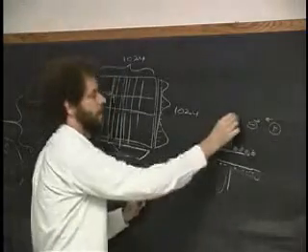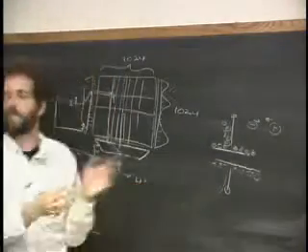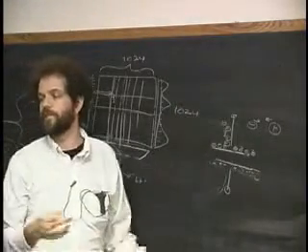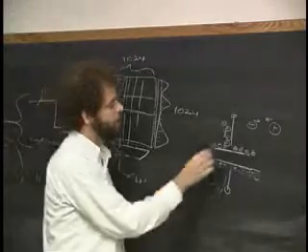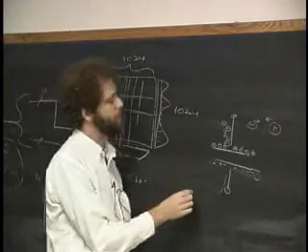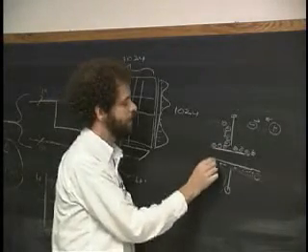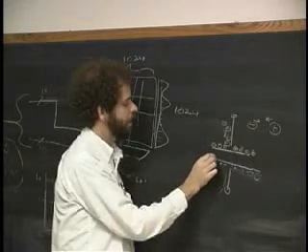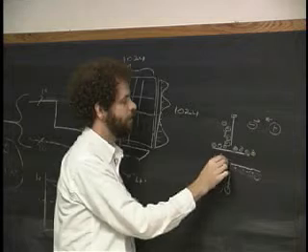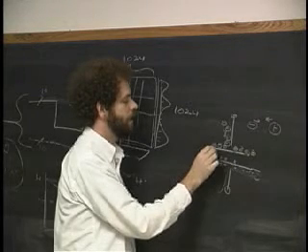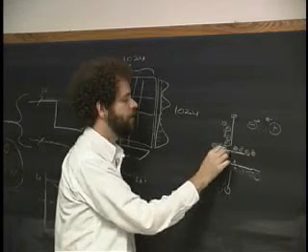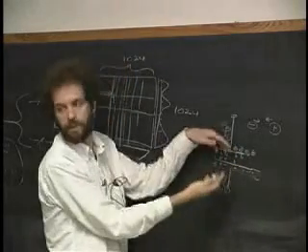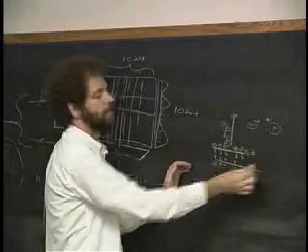So this thing is just standing by itself. Why does this thing stay like that? Well, the first answer is that there's nowhere for these guys to go because the circuit's open. But the other is that the negatives here want to get to the positives, and the positives want to get to the negatives. So these guys, seeing these guys a short distance away, try very hard to get towards each other. So there's a force that pulls them towards here. And these guys try to get towards here, so there's a force that pulls them towards here. And so you get these forces that are blocked by the fact that there's an insulator here.